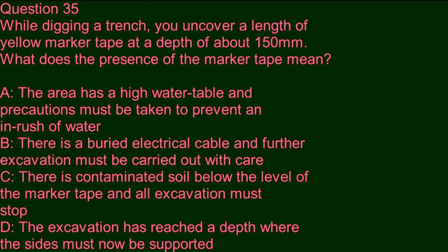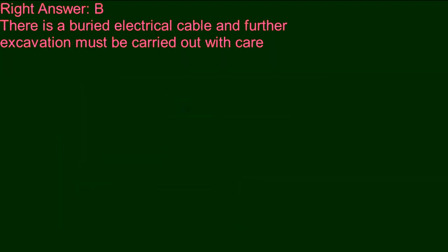C. There is contaminated soil below the level of the marker tape and all excavation must stop. D. The excavation has reached a depth where the sides must now be supported. Right answer, B. There is a buried electrical cable and further excavation must be carried out with care.